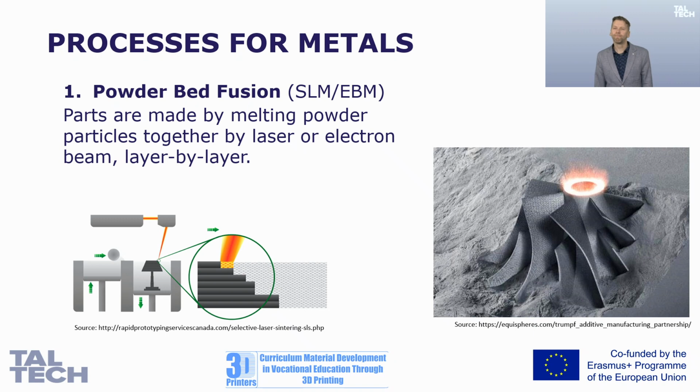Here there are some specifics when compared with plastic printing. Here we need, for example, support structures to hold the parts in contact with the base plate, because the temperatures are very high, and thermal expansion and these effects might change the part position. That's why we need supports.